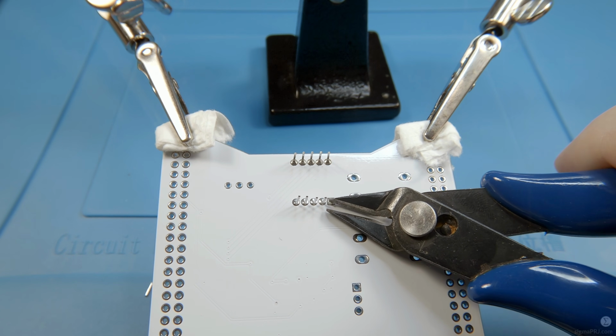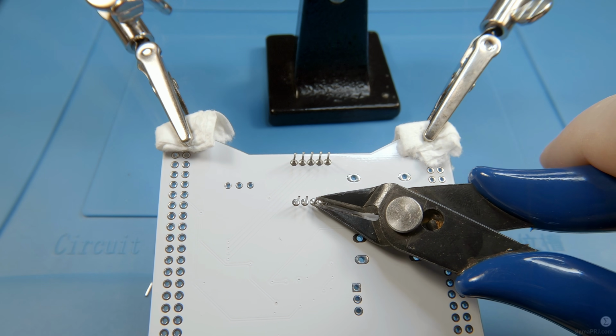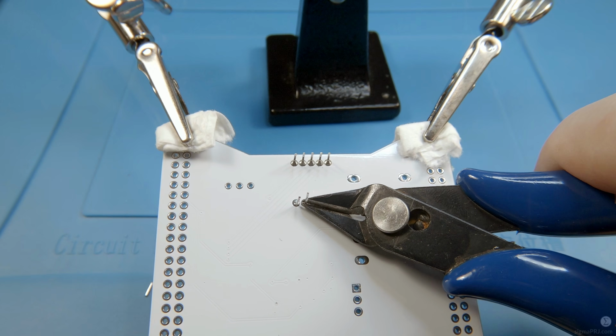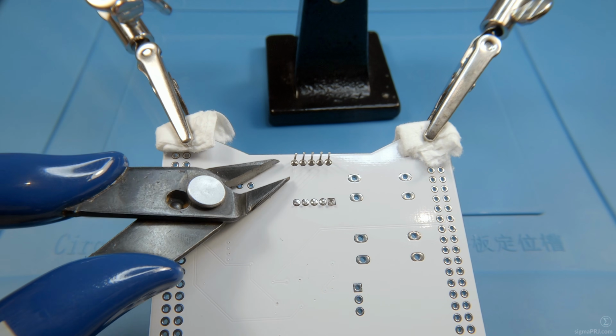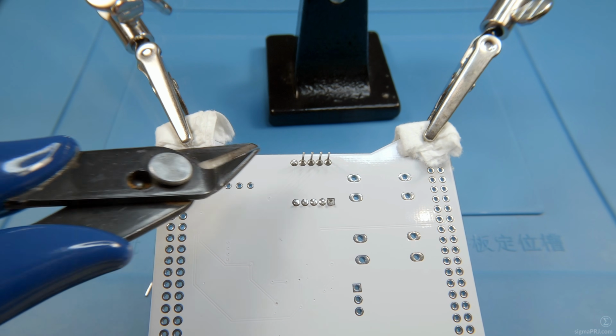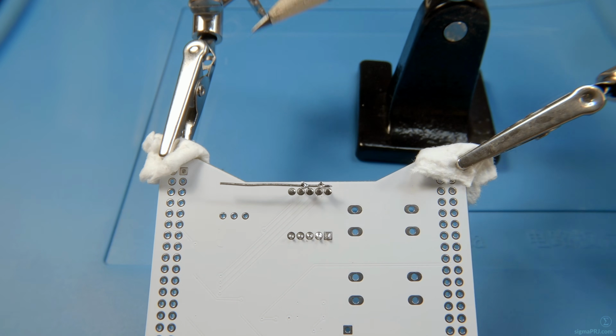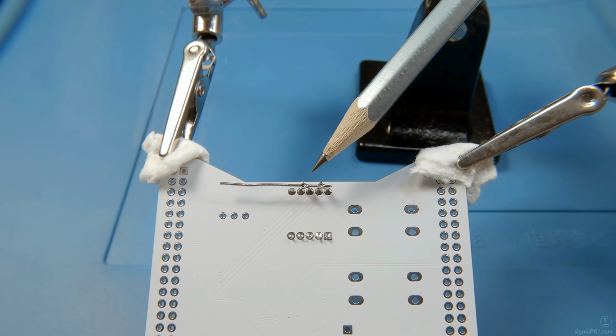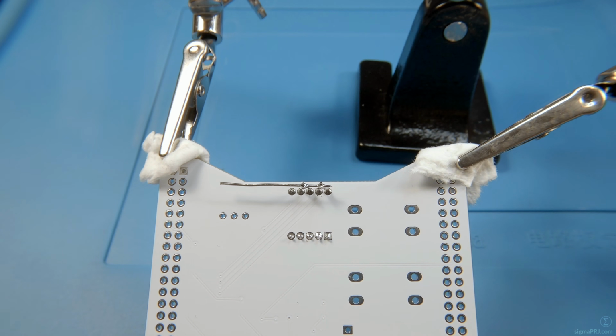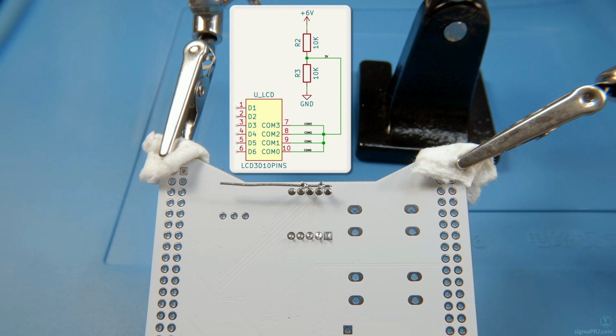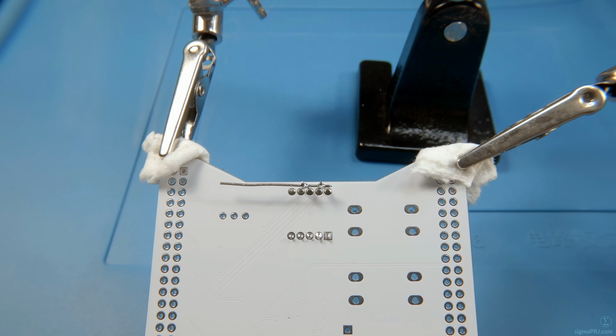Once soldering is done, we can trim these legs, but I would like to keep a few of them on the top row, exact pins which are connected to 4 common lines. Here I have connected them together, and we can use it to make basic LCD testing. They will be connected to 3 volts common level, which can be produced by a simple voltage divider. LCD signal pins at the same time can be connected to a square wave generator.